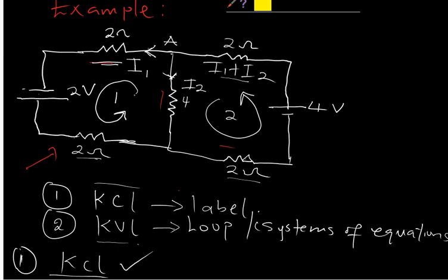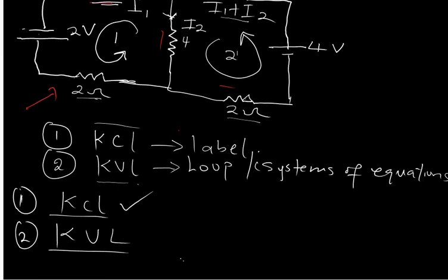If we sum the voltage around the loop, the sum of the EMF around the loop is equal to 0. I told you the reason it should be equal to 0 is that some of the voltages will be negative, right? They will have negative value. Now the question is, how do we know which voltages have negative value? That is exactly what I want to show you now.